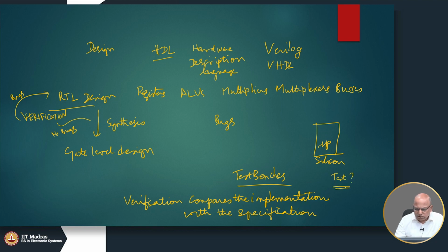Please understand that there is a difference between verification and testing. Verification is what we do when we are still in the early stages of design. We do not have any silicon. We have a Verilog file or a VHDL file which describes the hardware that we intend to manufacture, and we have written test benches and we are trying to remove the functional bugs.